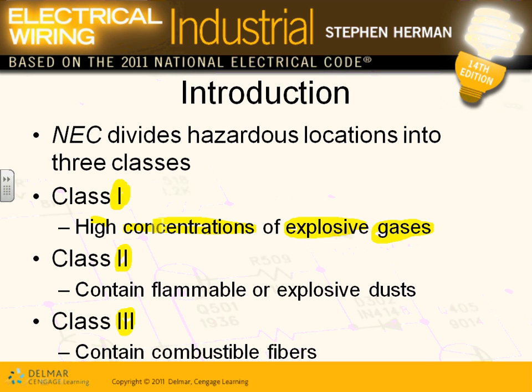Third, you have to have enough concentration in the air to be explosive, or flammable. So that's a major part. First, you have to have the flammable gas. Second, you have to have the concentration. You might have a flammable gas, but not the concentration. That doesn't qualify as a Class 1 location.